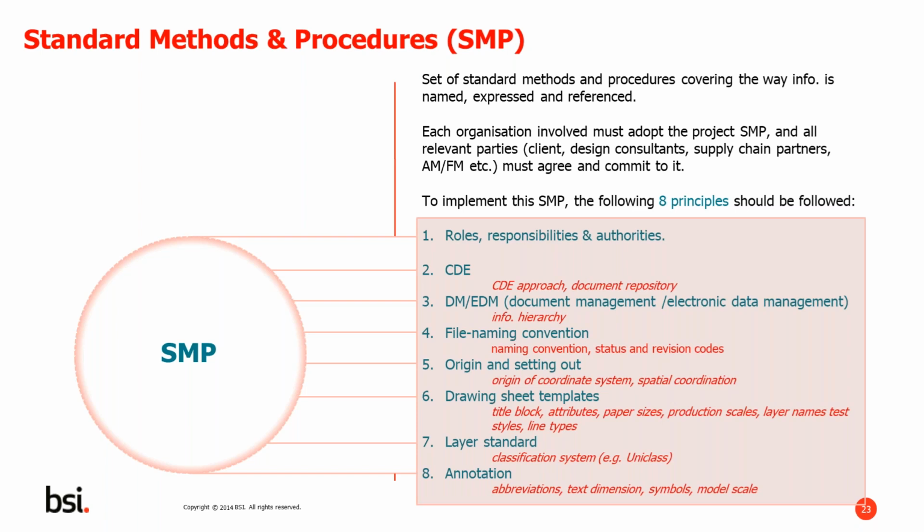You have your roles and responsibilities and authorities, the CDE approach and the document repository approach, your document management system and your electronic data management information hierarchy, your file naming convention, the origin and setting out of coordination systems and spatial coordination, your drawing sheet templates, the layer standard classification system, e.g. Uniclass, and annotation, so abbreviations, text, dimension, symbols, model and scale. Once those 8 principles are agreed and everybody in the project uses them, it enables the process to be much more fluid.